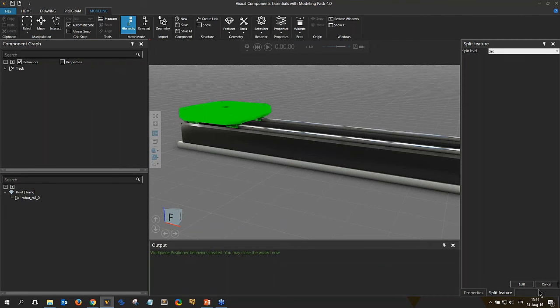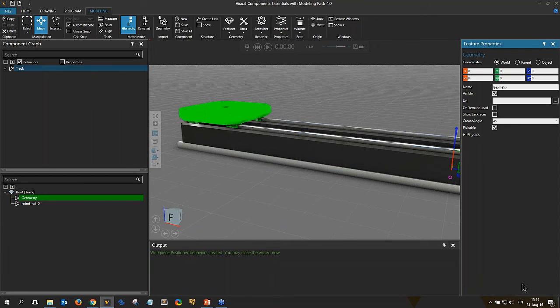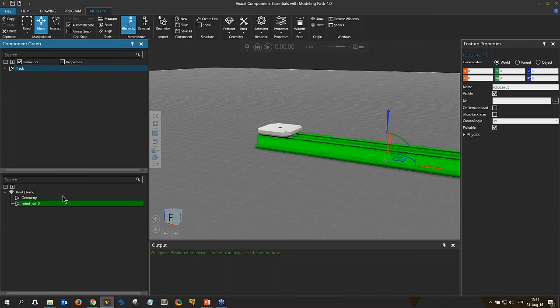With heavier models this might be a little bit labor intensive process, so it takes time, but just learn to be fast with your navigation and selection, and you will probably nail it pretty fast. Then I hit this split button on the lower right corner, and it splits that geometry out of this geometry.